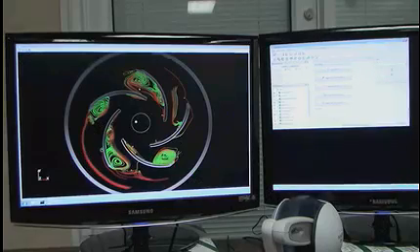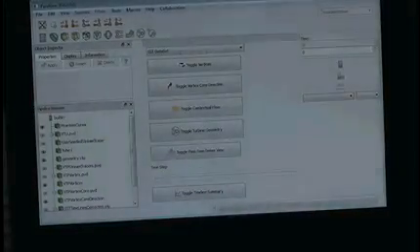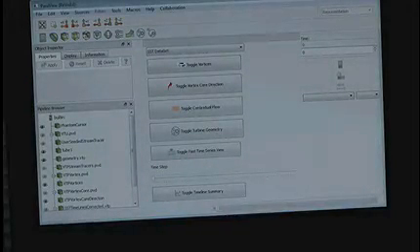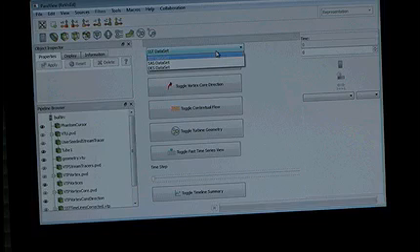We developed a vortex visualization workbench to assist investigation of the complex structures created by CFD simulations in centrifugal pumps. This workbench is built primarily on open source platforms: Paraview, VRPN, and VTK. This workbench can be used to analyze datasets from the SST, SAS, and DES simulations.